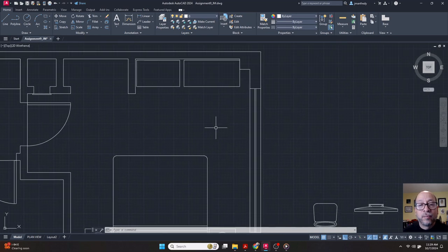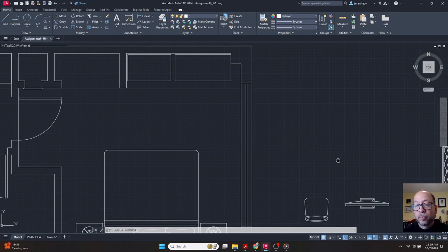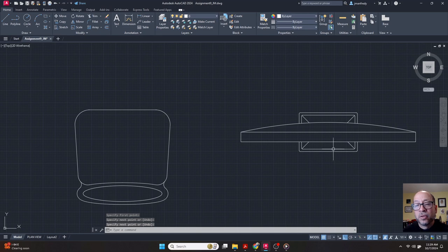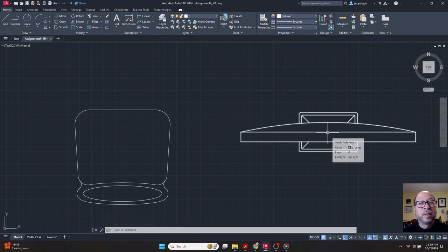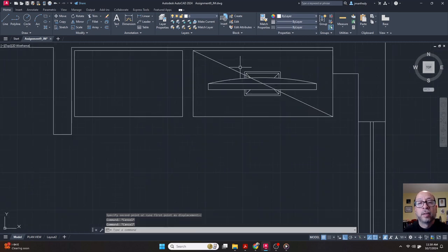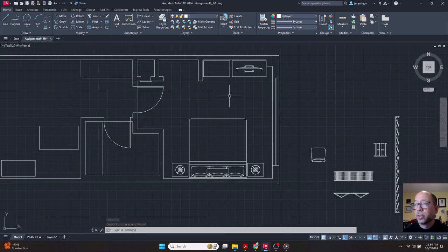The TV, again, if you care about centering the TV, you can, or you can eyeball it. In this case, I'll draw a line from the center of this to the center of this, and then use that to snap the center of the TV. I'll use this line here of the TV to center it on that line I just drew. Move, click, snap to the midpoint, and then here, find the midpoint there with a little triangle. Click. I then no longer need this line here. Delete. And so there you're on your way to producing this design here.